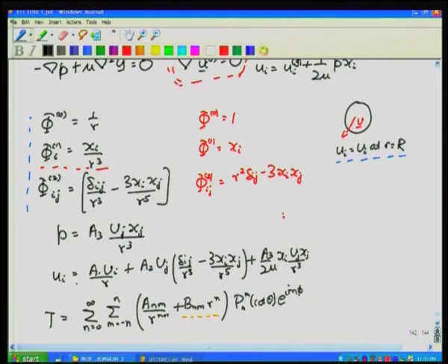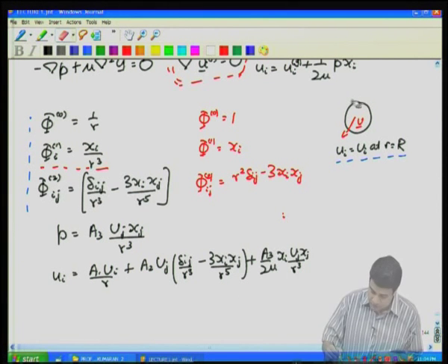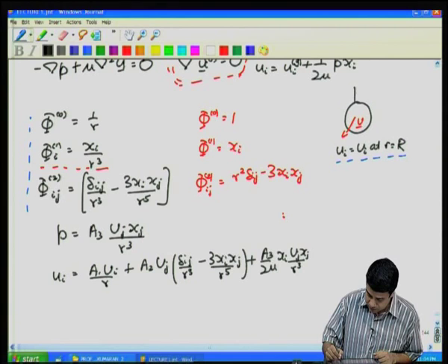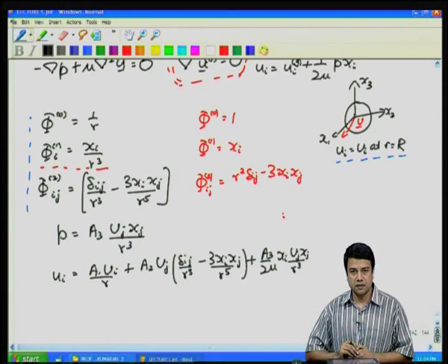In the last lecture we had derived the equations for the flow around a sphere. And in that case if you recall, we had used only the decaying harmonics. We had placed the origin of the coordinate system at the center of the sphere, and then use this in order to evaluate the equations for the velocity field due to this solution.